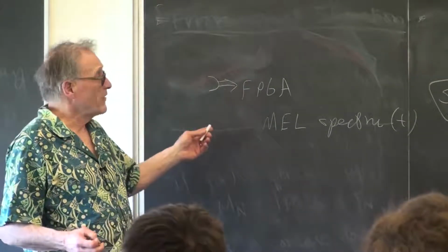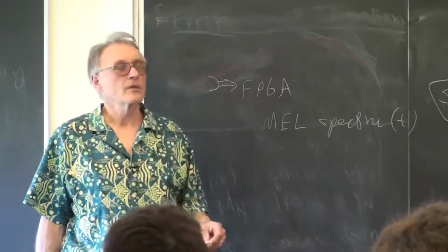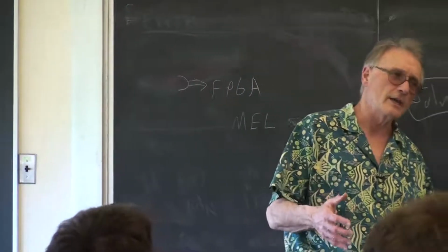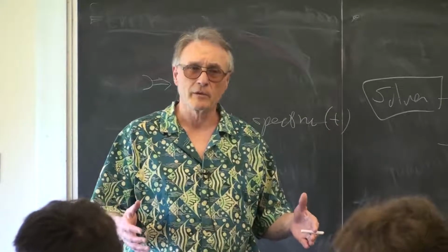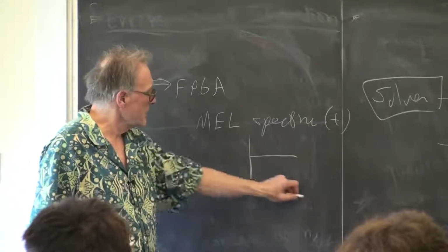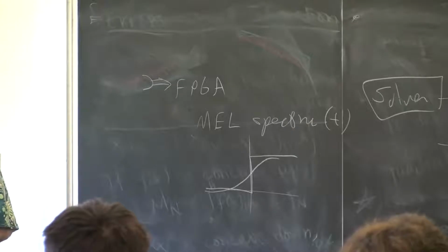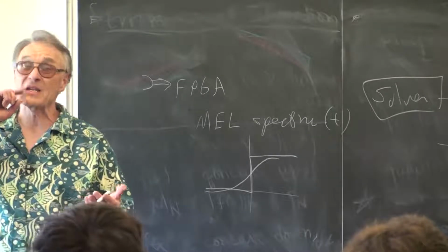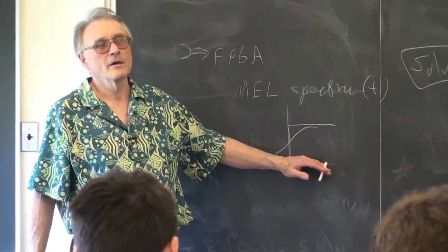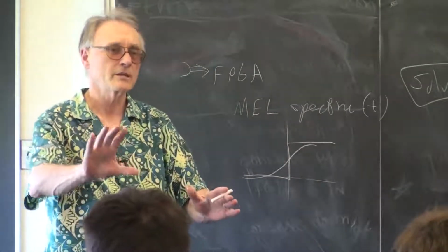Another possibility for an FPGA application is a neural net. And if you Google FPGA neural net, you'll find that there's all kinds of approaches for fitting rather large neural nets into rather small FPGAs, like using binary weights instead of floating point weights, or using binary decision functions instead of sigmoidal decision functions, which are expensive. So in that case, you might put Mel spectrum plus some piece of neural net on the FPGA side to drop the dimensionality even further, so that the HPS has to look at a fairly small data set for doing template matching.